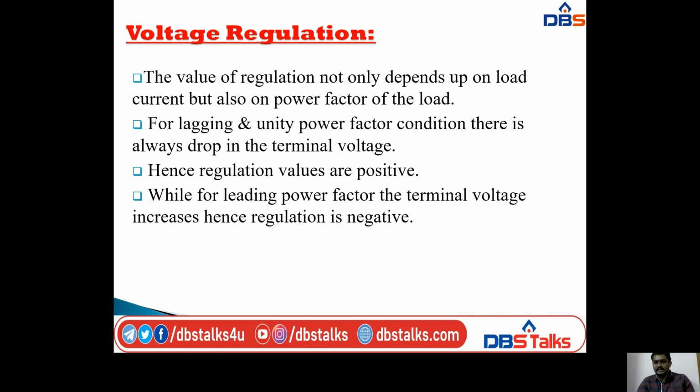Next, the value of regulation not only depends upon load current. Actually the voltage regulation mainly depends upon load current, but here it also depends on the power factor of the load. I already discussed these things in the armature reaction: unity power factor load, zero lagging power factor, and zero leading power factor loads. So here also the value of regulation depends upon the power factor of the load.